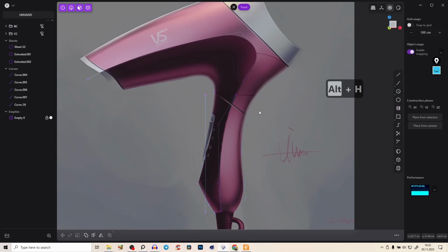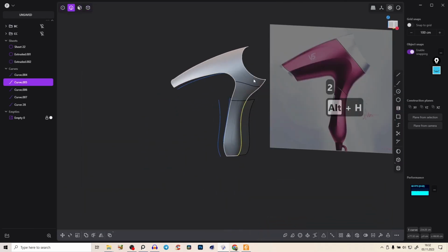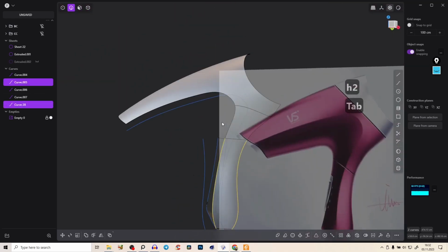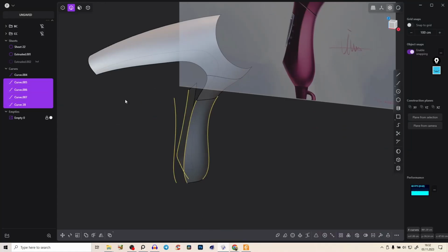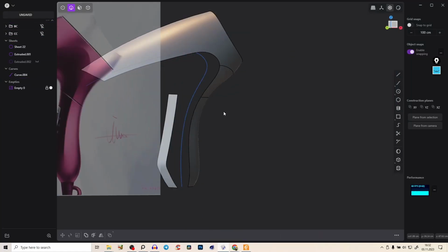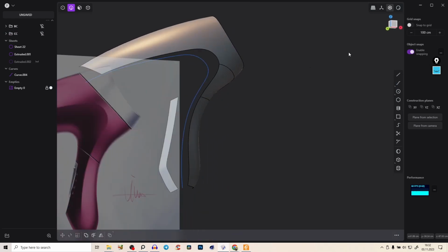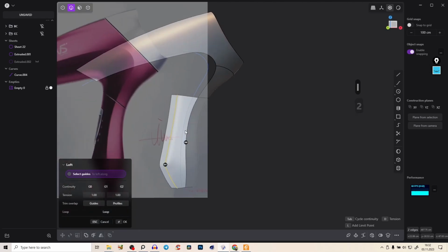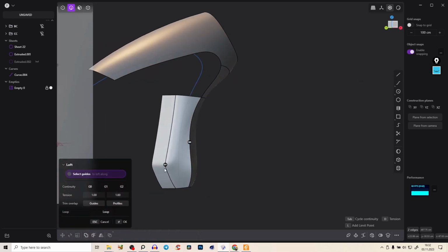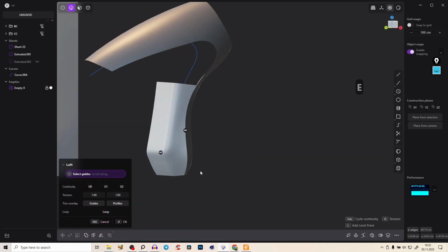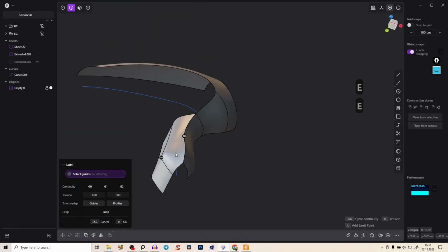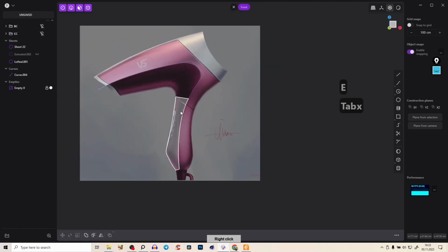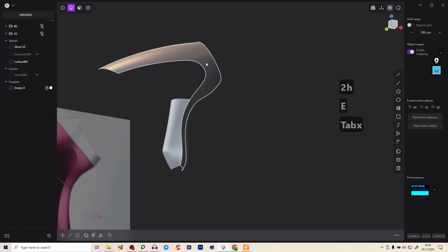All right, so let's press Alt H and bring everything back here. We don't need this sheet here and we don't need those curves. Those 3 curves here, those 4 curves, put them into BC. And now we want to loft these ones too. Here give it G0, as you remember, because we have a sharp edge. And here maybe G2, but again you can play around here and create some manual curves. But yeah, that's fine here. So delete this curve. So you see we are getting somewhere.